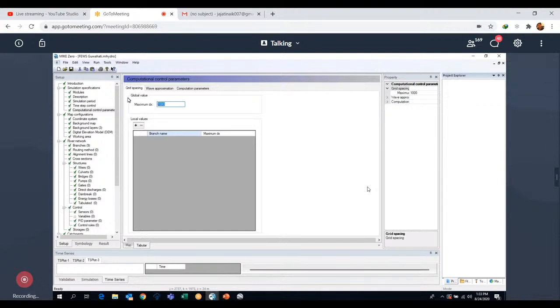Okay, and whatever is in between those cross sections will be calculated discharge. So like the previous speaker has also explained, you get water level at 2 cross sections and you get discharge in between 2 cross sections. So that's how we do the calculation here. It's the 6-point Abbott equation that we are using along with the Saint-Venant equation to solve this finite difference equation.